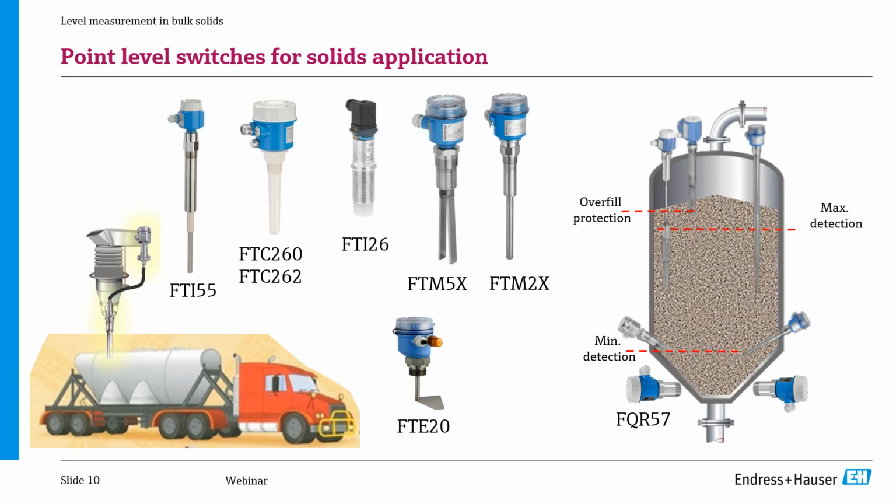So the first approach for an effective control, at least from an instrumentation perspective, are the point level switches. There are several types of sensors available that range from vibronic sensors, which are these ones here, and capacitive sensors, to even non-contact measuring options such as the microwave barriers that can monitor the presence of product through a non-conductive material such as, I don't know, a polymer or even glass. All right, so these are very interesting. And what defines which one to use? Basically, the installation point